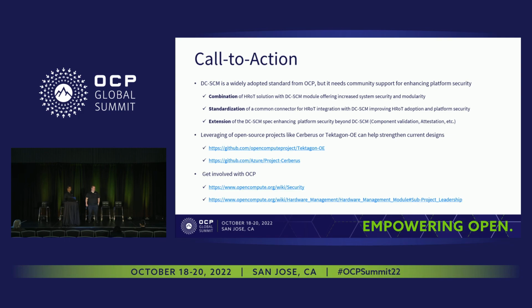So how do you see us increasing the profile as an industry for the other components, be it component attestation, be it an extension of what the FPGA could do more so than what the BMC does today? No, you're absolutely right. The FPGA has a lot more flexibility in that the I/O isn't necessarily defined for it. So you can use additional pins or upgrade to a higher-end FPGA to do additional monitoring and other things for these additional components.